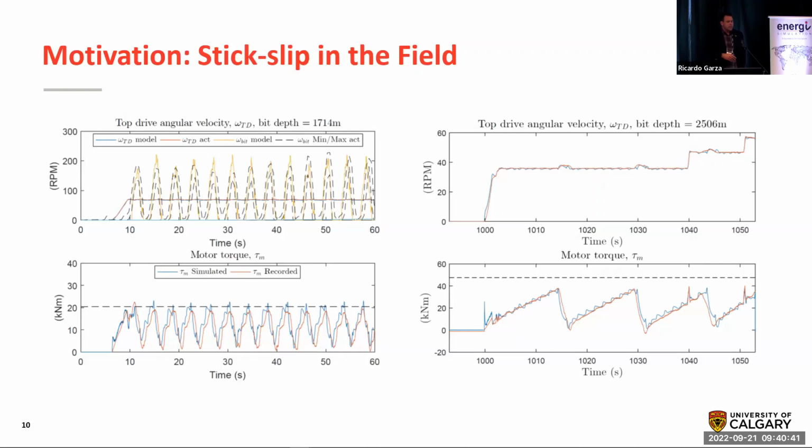And then that oscillating sine wave is your downhole RPM. This well had a high frequency data sensor in it that was recording on memory. You couldn't see this in real time. You saw this two weeks later when the sensor finally came out of hole and was downloaded. So a very, very cyclic pattern downhole. And then at the surface, your torque, so the energy that's going to the system, has that nice symmetric saw wave. The example on the right is also stick slip, but has a slightly different character. It's a slower buildup, faster release, slower buildup, faster release.